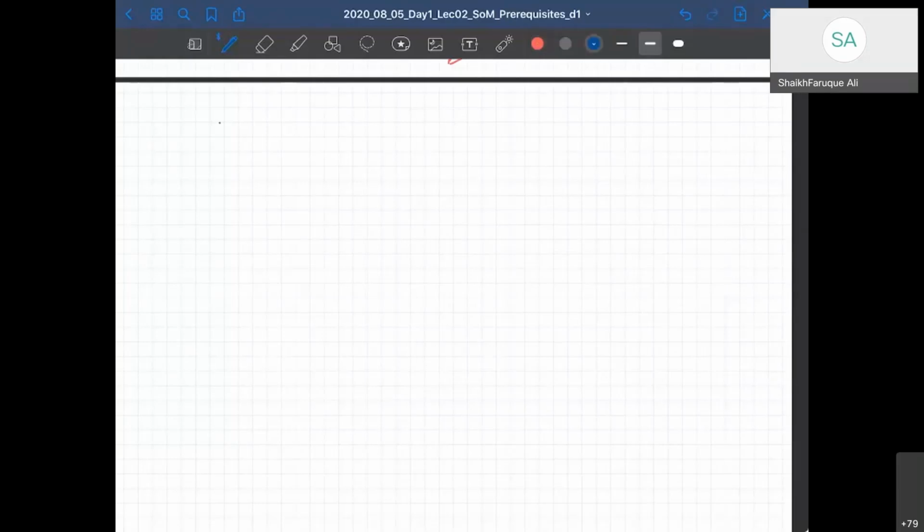Now let's look at a single simply supported beam. Okay. This time I am not going to solve it. You are going to write it in the chat, or if you want, you can just open up and say, not a problem to me. I have a force here. All right. Can you now tell me what its boundary conditions are? First thing is I have to name point A here, point B here. I have only two boundaries, point A and point B. Now tell me the boundary conditions.